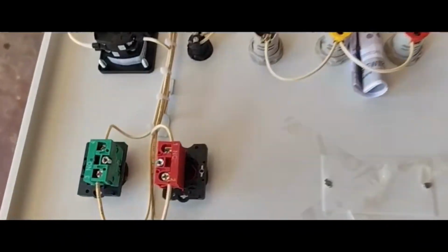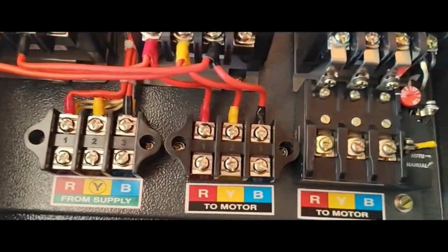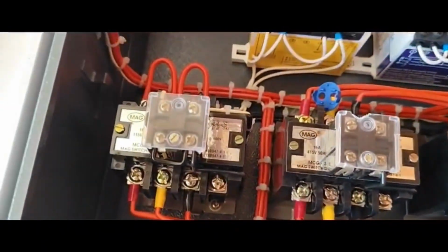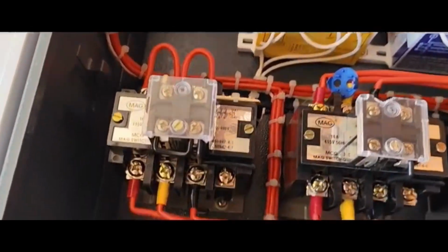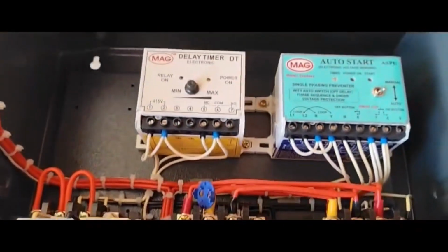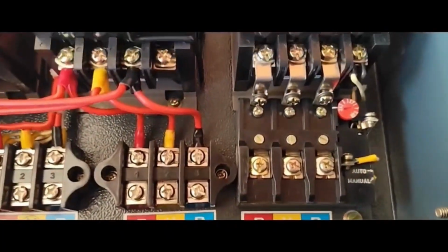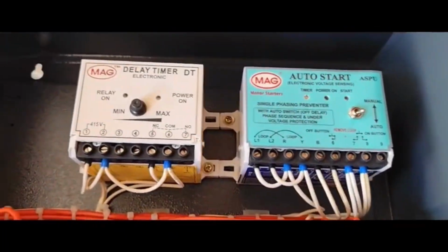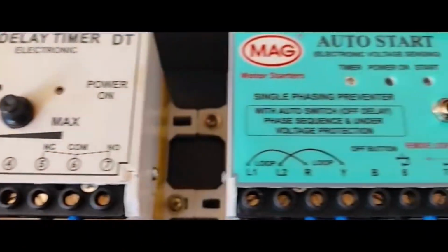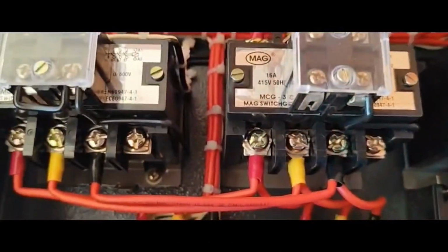In this video, we see advanced knowledge of circuit connection, including circuit analysis subject, analytical machinery subject, and control system subject. The figure shows the contactors. The first contactor acts as the main contactor and star contactor. That is an important role. The second contactor acts as the delta 1 contactor. The third contactor acts as the delta 2 contactor.